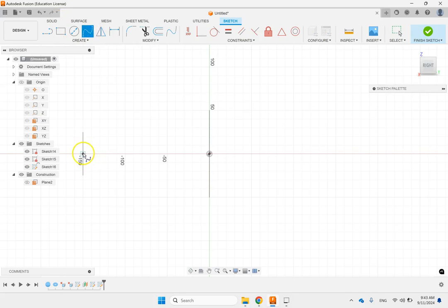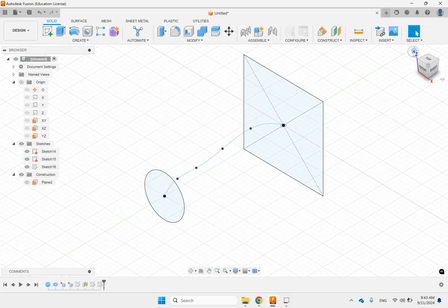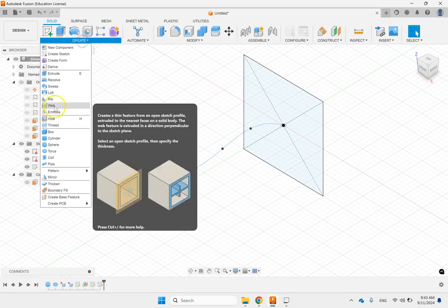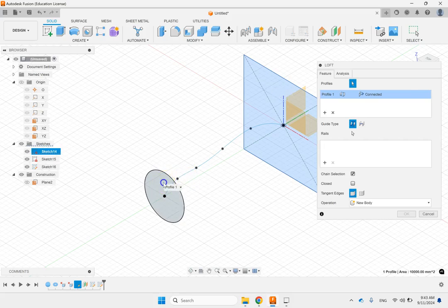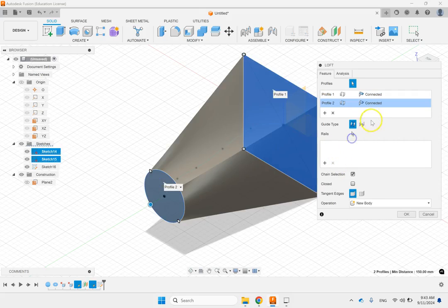Seems like I turned the command off instead of double clicking, and let me remove the big curvature. There we go. So can I connect them with something like this instead of a simple line? And by the way, you make sure that this center curve intersects with the profiles. So let's go ahead and see what we can do now. And loft again. For profiles, I pick this and I pick that. And for rail, I say I want a center one and I pick this.